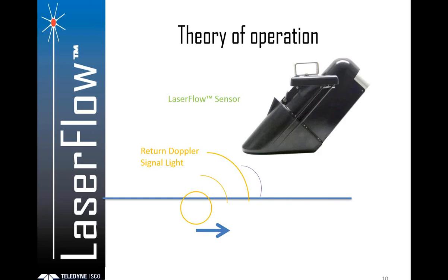One thing that the video didn't mention is another unique feature of this sensor: we have the ability to face or position the sensor upstream looking into the flow, or looking downstream into the flow. So that really gives you a lot more flexibility, because in some situations you may not have a good read looking upstream, where you have a much better channel profile looking downstream. So this is kind of what was described in that video and how things work with the subsurface velocity measurement.